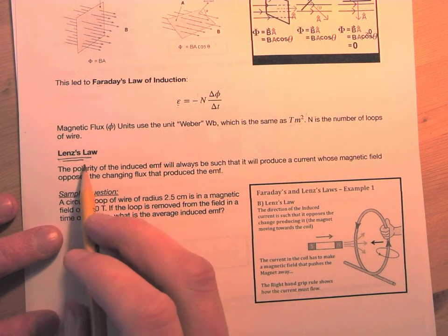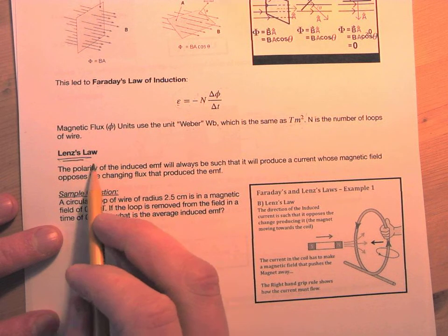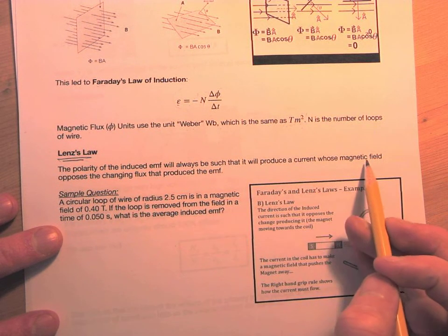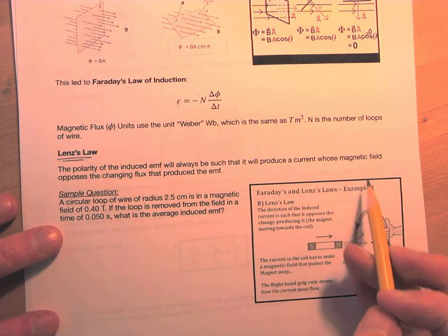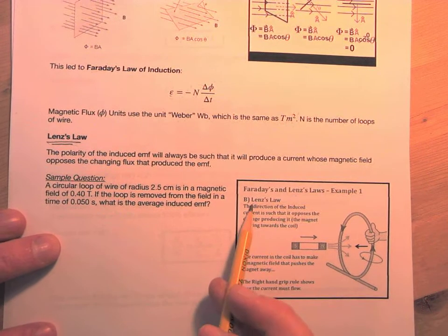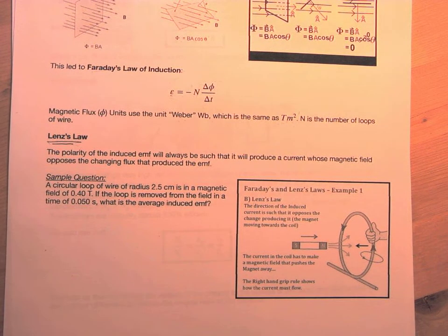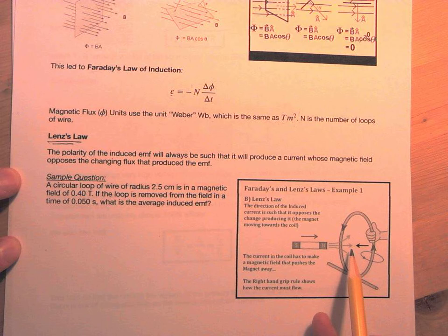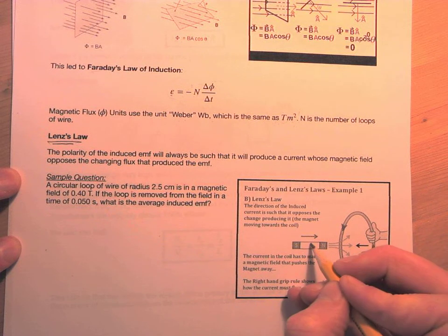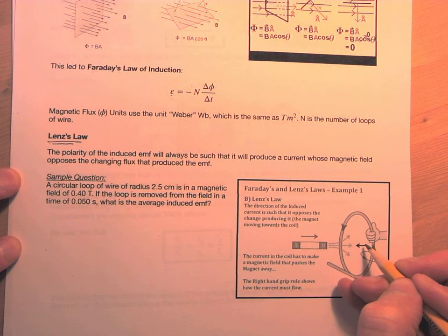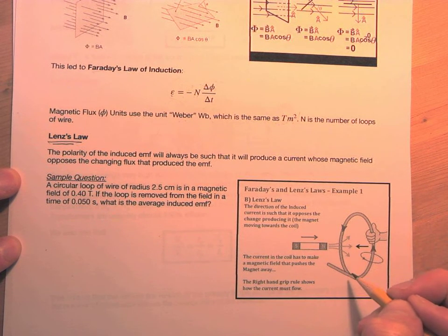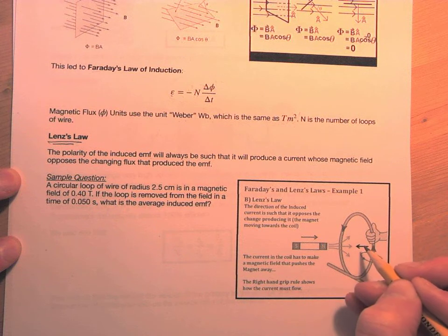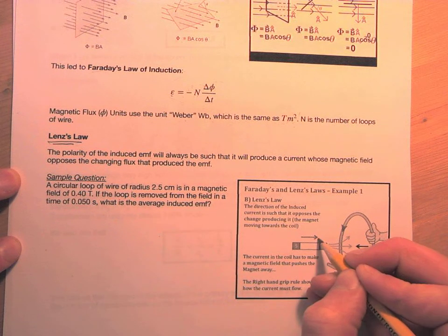So essentially there is an opposite voltage charge that happens when you make movement. Okay, so an example here is Lenz's law. Say you don't have a current in this wire and you move this magnet inside the wire, or you move it in this direction here. Since you're moving the magnet in this direction, Lenz's law says that the current that's going to happen in this wire has to make a magnetic field that opposes that movement.